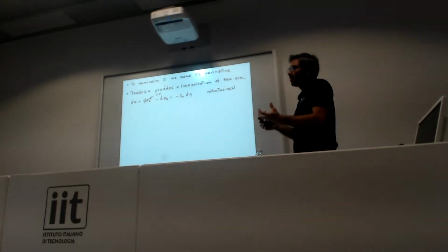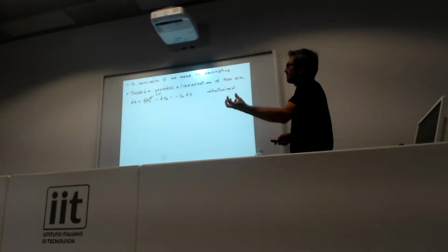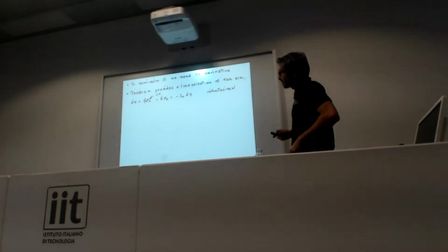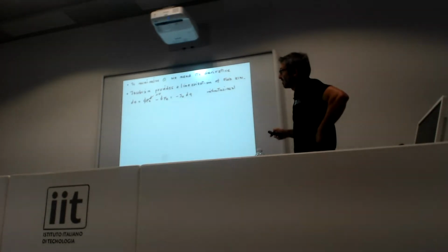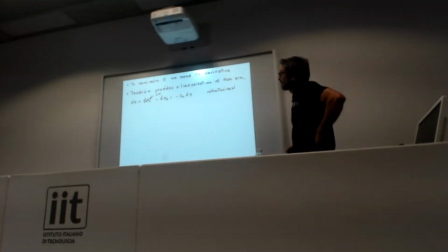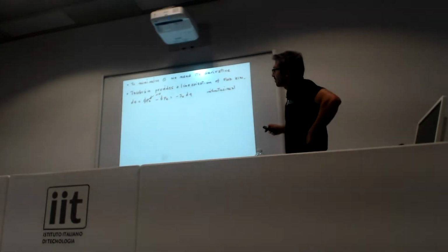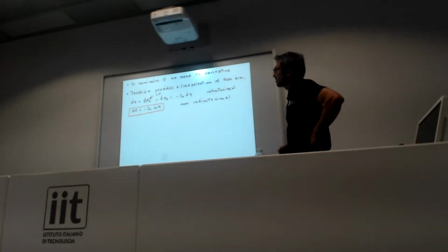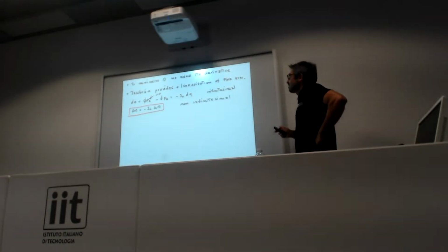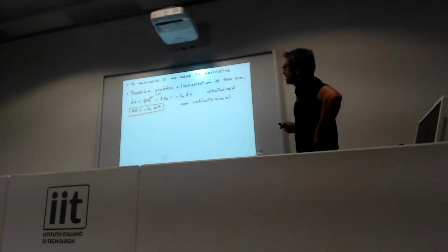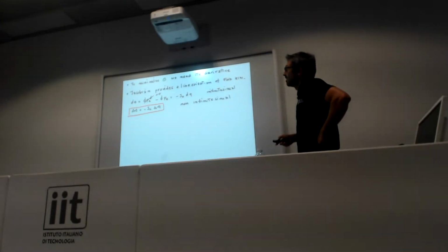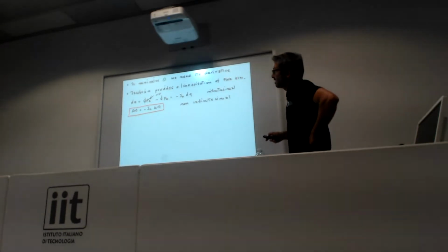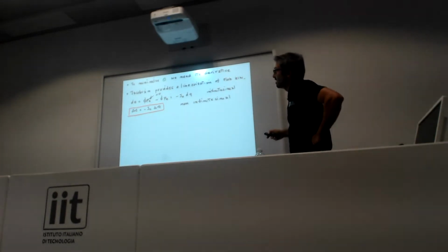In the desired point, in this case, it's a fixed point, so it's 0, minus the derivative of the end effector point, that is Jacobian times delta Q. And if we don't consider infinitesimal variation, we can get the same relationship, delta E equal to minus J delta Q.